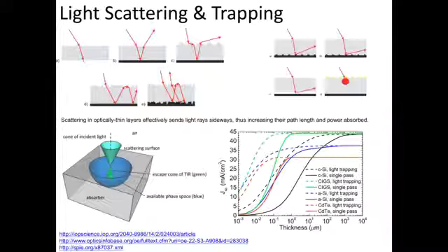You get reflections that essentially ricochet through the device, so you get many more passes. The light gets passed through the device many more times, and so you increase the collection probability. Here, this shows an increase in current by increasing the path. Using textured surfaces to increase light, you can increase current significantly, simply because you're absorbing many more photons.